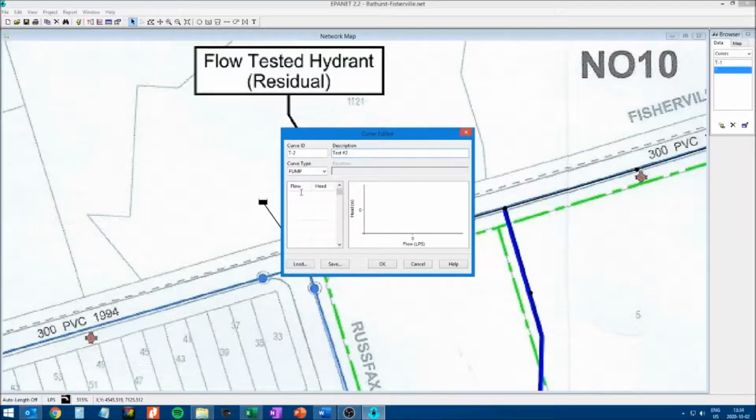Again, keep the pump curve, and for flow test number 2 we had the static condition, so 0. Then we had 65 liters per second flow, and 94 liters per second. At the static condition they measured 50 psi. Convert that to meters of water, add the node elevation, and that gives 228.04. At 65 liters per second we are at 225.93, and at 94 we are at 223.12.